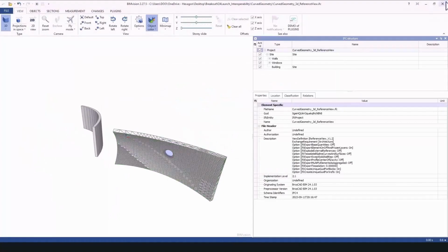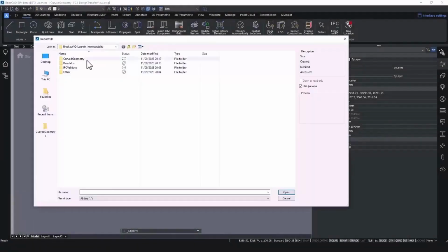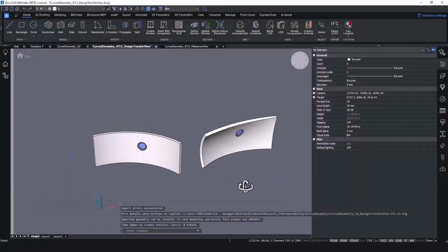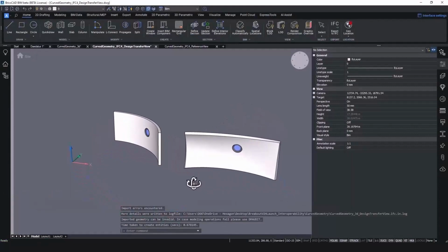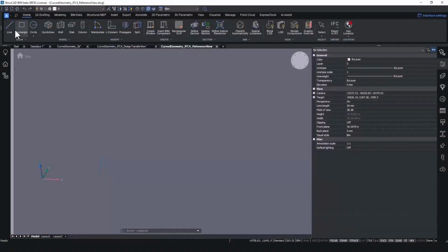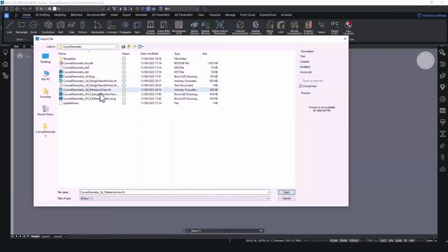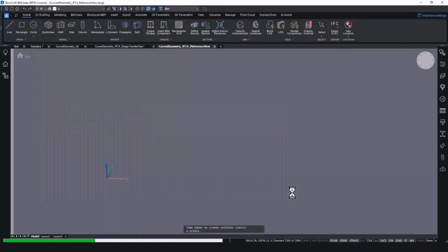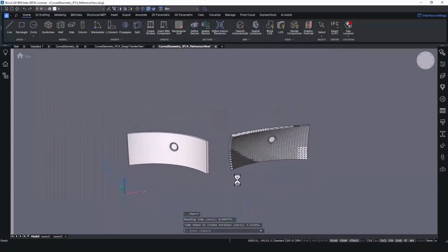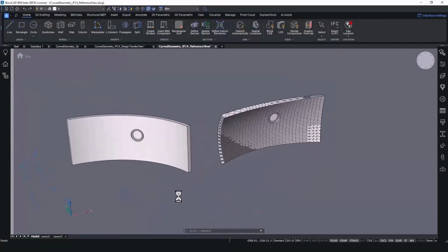Now let's see how BricsCAD handles this. Because in essence, the design transfer is still the best way to transfer your models in a full way without simplification. As you can see, when this curved geometry is imported back into BricsCAD, the IFC4 design transfer view is actually more accurate. However, the IFC4 reference view is a simplification or an approximation of certain curved geometry. This makes that more programs can read it, especially because they are certified against this reference view schema.